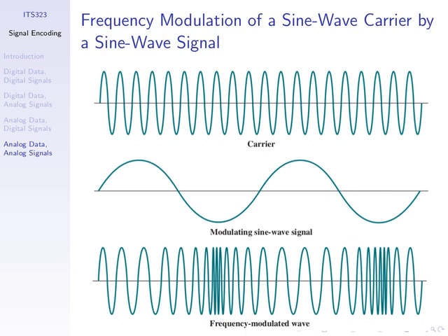So whenever we're transmitting analog signals, we either change the amplitude, phase or frequency. But there's shift keying and modulation. Understand how sampling works. The trade-offs between the sample rate and the code numbers, the number of levels. And understand how you'd interpret the different encoding schemes, such as Manchester encoding, converting digital data to digital signals. That finishes this topic and finishes for this week.